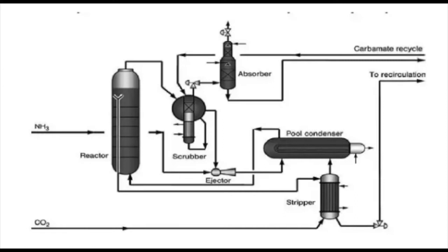Now looking at the process flow diagram, all the condensate from the evaporation section is then treated in desorption and hydrolysis sections. Ammonia and carbon dioxide are stripped off in a top desorber column, and small amounts of urea are dissociated in the hydrolysis column. The treated condensate can be used as make-up water for cooling water cycles because of its high purity. It could even be used as boiler feed water after polishing. Thus, the Stamicarbon urea process has no waste water effluent.